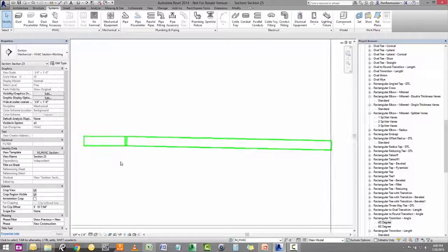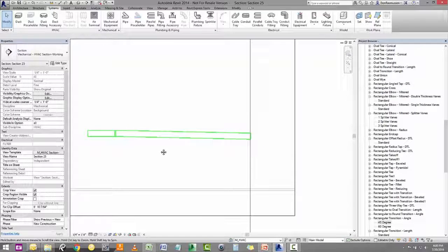So really the goal here would be to be able to model in slope ductwork to the point where you can get some of the bigger coordinations ironed out, make sure things fit in some congested areas, as oftentimes grease duct unfortunately is an afterthought in some of the jobs I've worked on. So just to show you guys here, it is possible, you can do it, you can design with it. It is limited though with some of the functionality as I just demonstrated in regards to the slope and how that all works. So we'll get out of this for now,